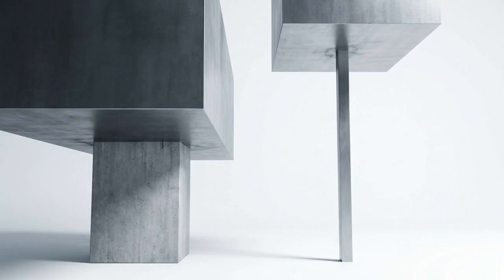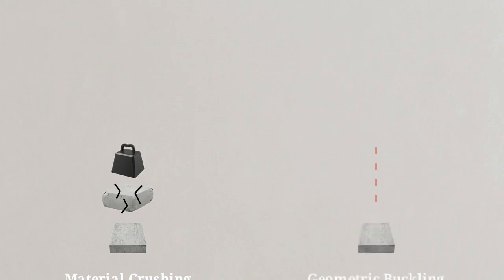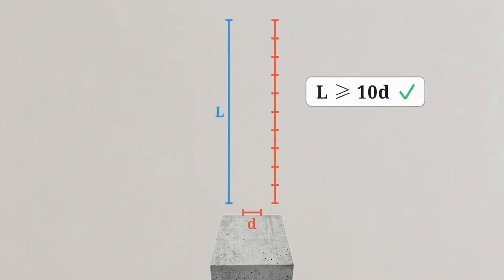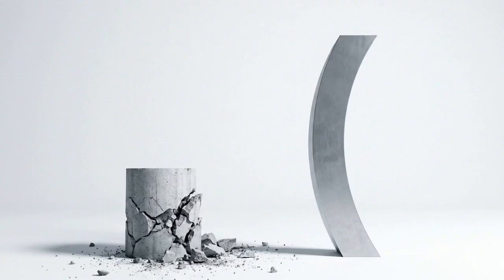In structural engineering, a column's entire job is to take a heavy compressive force from above and transfer it straight down to the ground. Engineering columns are defined by their relative proportions. While a short, thick block will eventually crush under load, a true column is long and slender enough to introduce the risk of lateral failure. The standard rule of thumb is slenderness. If an object's unsupported length is roughly 10 times greater than its narrowest width, it behaves like a column. The moment a structure stretches past that physical threshold, its rules of survival change entirely. The threat shifts from crushing to buckling.